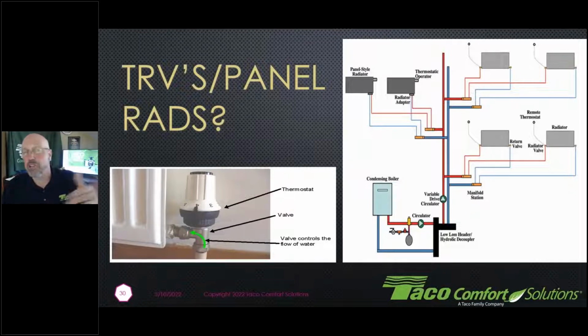Another term that we might use for this would be constant circulation, meaning the circulator continuously runs the entire winter because these TRVs are always putting just a small amount of heat into your space. If you remember from previous classes, these are typically operated on a 30 or 40 degree delta T across our system. So our flows are relatively low and we end up with a little bit higher head as our flow starts to increase.